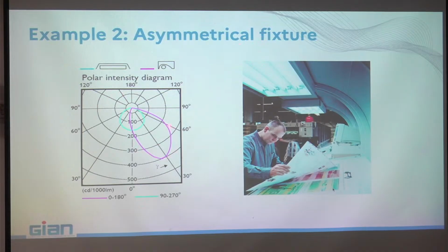And of course you use fixtures sending the flux here. Okay? You illuminate from behind, and you can even choose the angle of the maximum illuminance toward the direction here in order to avoid, for a standard height worker, the shadow from his head. That means the flux passes above him and then illuminates his working plan very well.